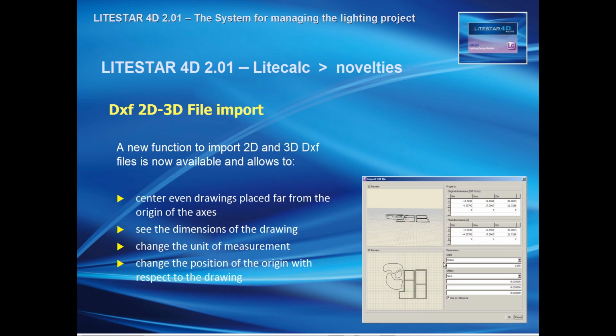Through the options we have here, for example, through the offset, we can move the absolute origin and bring it close to the drawing, so that the drawing will appear in this window.